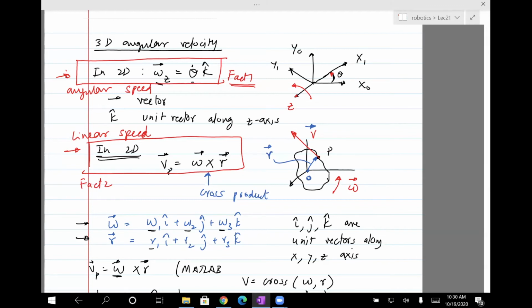So remember I talked about rotations in 2D to 3D. You can't just take the rotations about x, y, and z axis and just add them. We had to go through that rotation matrix. Similarly, when you do the rotation angular speed, you have to go through the rotation matrices to do this.